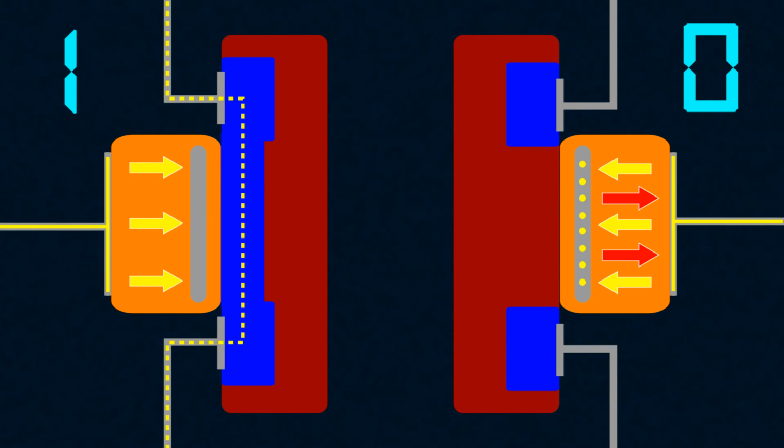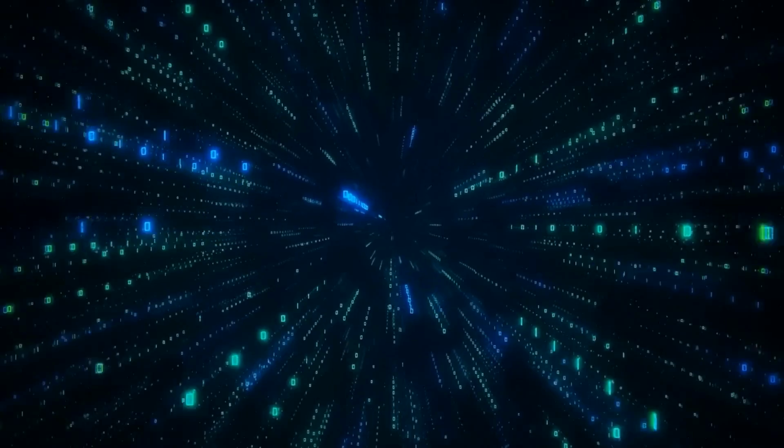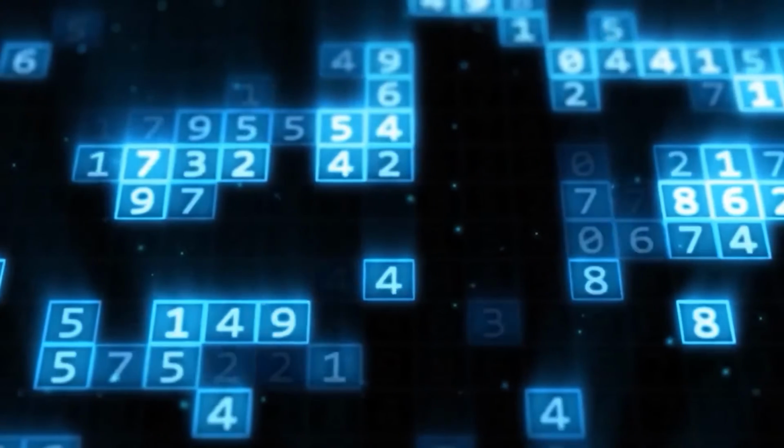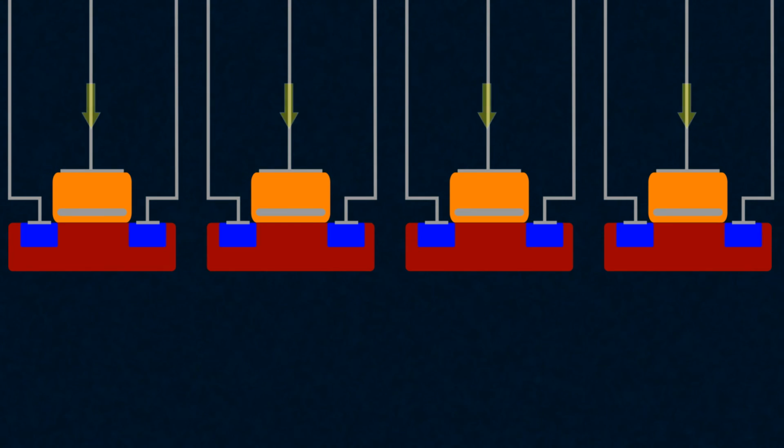But why should we limit ourselves to just the categories of few and many? Why not try to measure how many electrons we've pumped into the floating gate? And it turns out, we can easily do that by applying different voltages to the main gate of the transistor. Indeed, let's say there are practically no electrons in the floating gate, which means the transistor opens with the minimum voltage. We'll denote this state as 1, 1 in binary notation, or 3 in decimal.